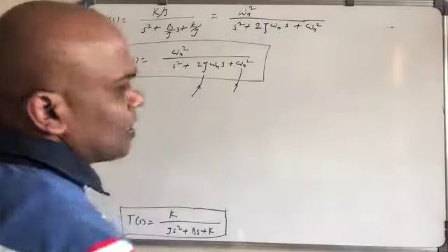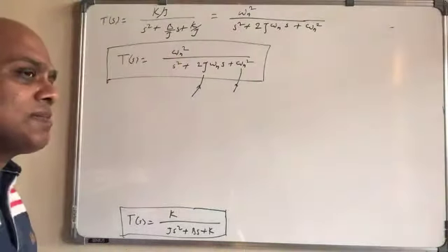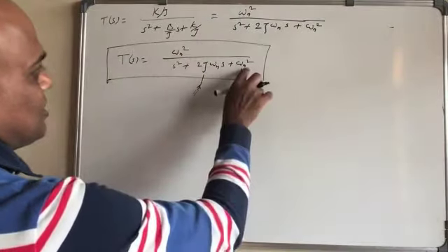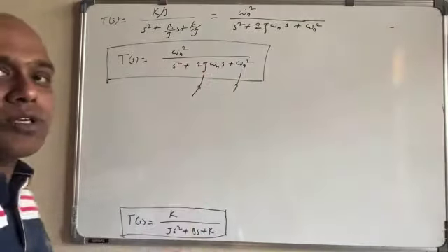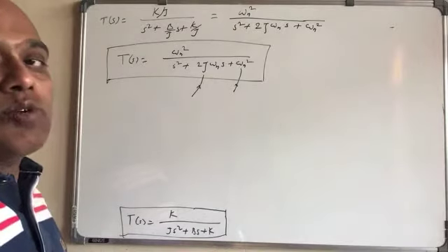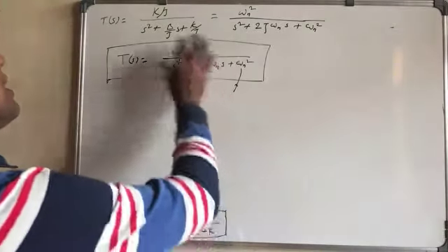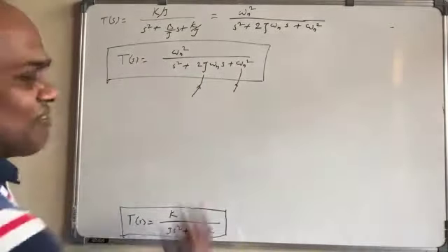From the second order system or the spring mass damper system, we know this is the damping ratio, this is the natural frequency, and the same kind of words we also use here, although this is not about the actual spring mass damper system, but an equivalent system which has a similar transfer function.